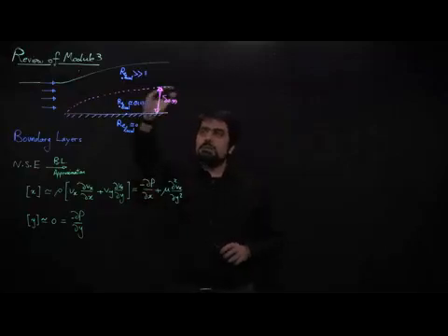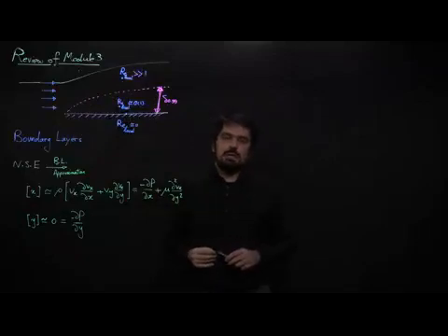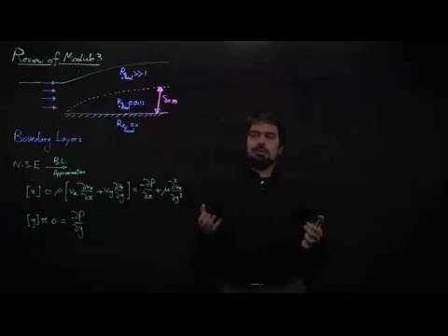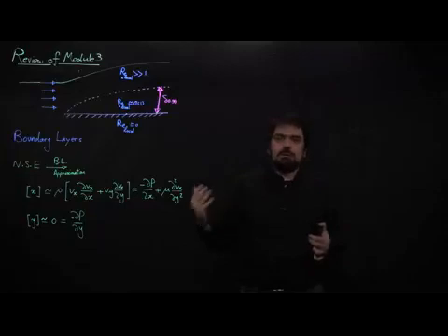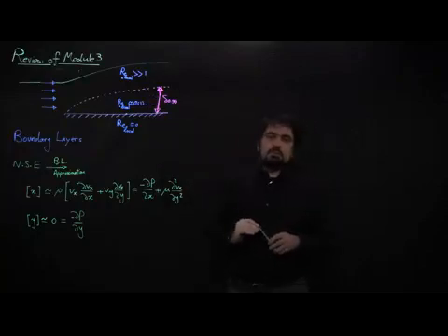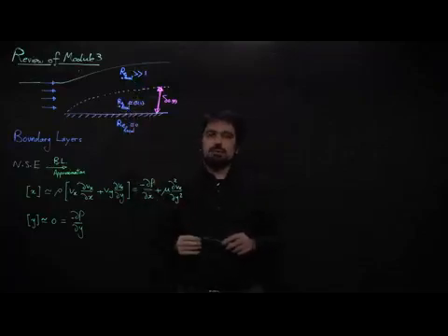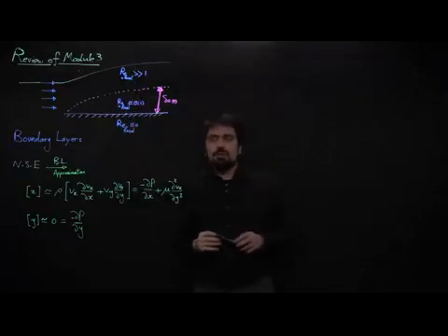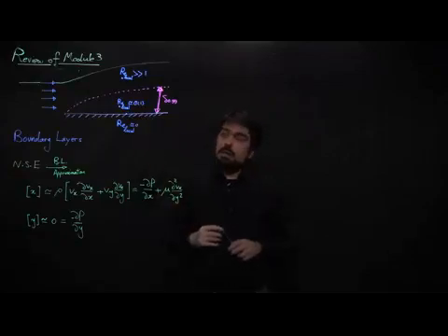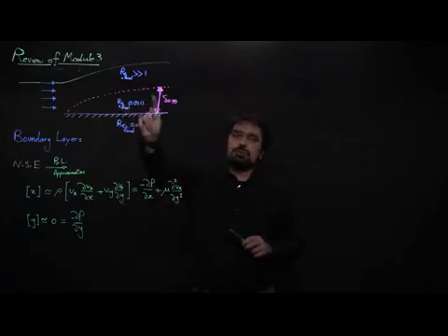This boundary layer is a mathematical way of dividing our problem into 2 regions and dealing with each region accordingly, based on a certain approximate version of the Navier-Stokes equation. In the outer region, viscous stresses are probably negligible, so we can solve the flow using potential flow. In the inner region, we have a different scenario. We cannot ignore viscous stresses inside the boundary layer, and at the same time we cannot ignore the inertia. They are both important because their ratio is of order 1.